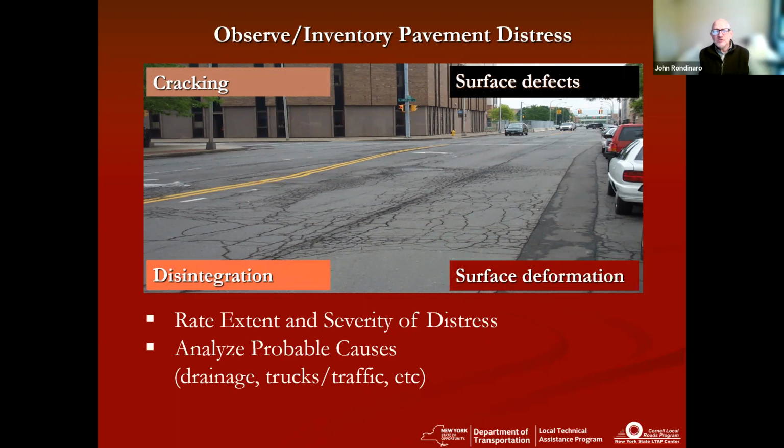In terms of the distresses themselves, you're looking at 4 major categories of distresses. You've got your cracking, so your typical longitudinal transverse cracking, your load-related, fatigue-related alligator cracking, edge cracking, reflective cracking, all those types of cracking that are going to be affecting your pavement. Once that cracking advances a little too far, you're going to be talking about disintegration of your pavement, and that's really where you develop potholes, and you're also counting in under disintegration wherever you've done any kind of temporary pothole repair.